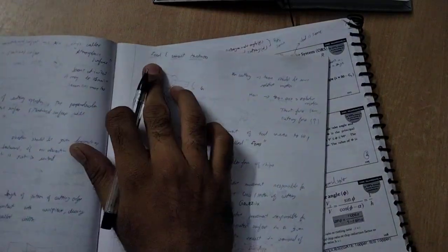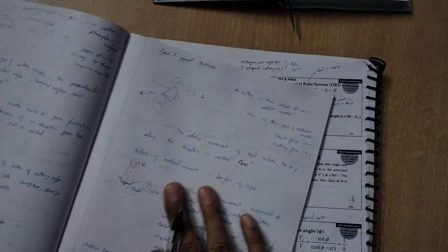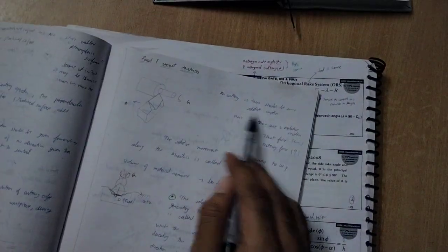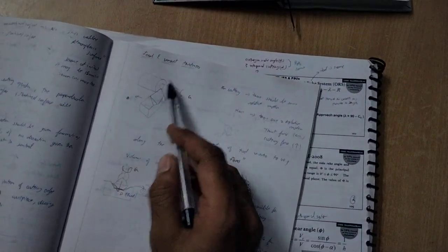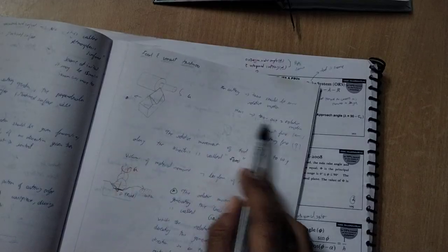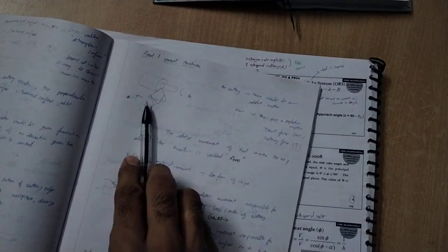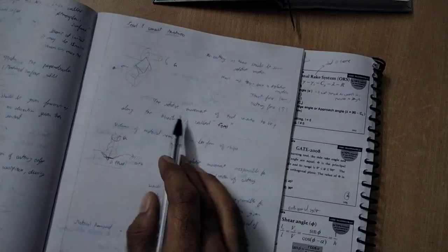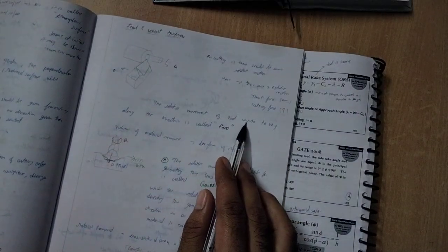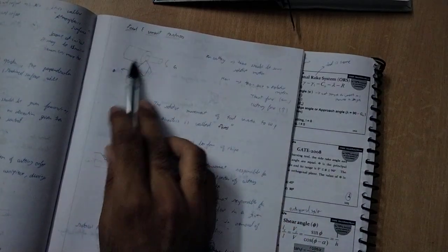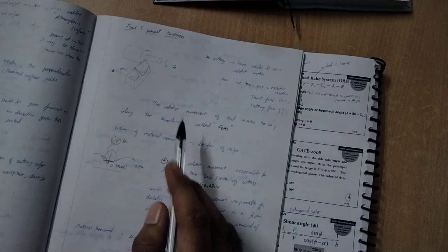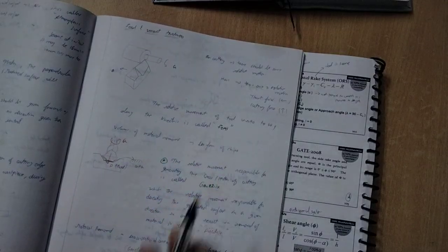So next one you can see feed and uncut thickness. Okay, for cutting there should be relative motion. So this also needs to rotate, this also needs to move. Here are two relative motions. You can see the thrust force goes here and the cutting force goes upward. Okay, the relative motion between tool and workpiece, it means the tool with respect to the workpiece along the direction is called as feed.